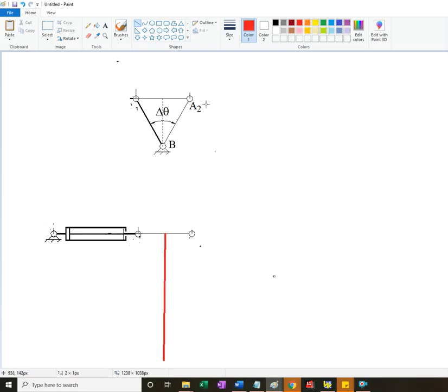And then what's left is for you to find where point B is, and if this angle is, say we start considering 80 degrees, you take half of it, it's 40 degrees, so it means that this will be 50 degrees, so you go and measure 50 degrees here.